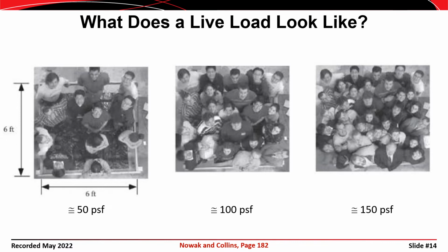So you might remember from our discussion of load combinations that when you get to a live load that's 100 pounds per square foot or greater than 100 pounds per square foot, there's some changes in the way that live load is considered. And that difference is basically based on the idea that areas of public assembly might actually see people that are crammed into a space as tightly as could be.